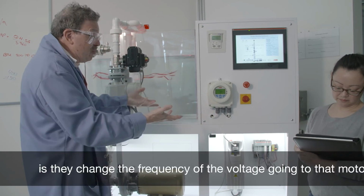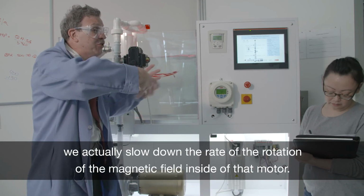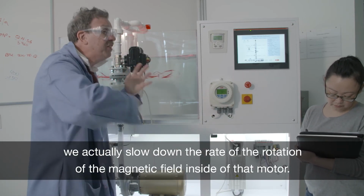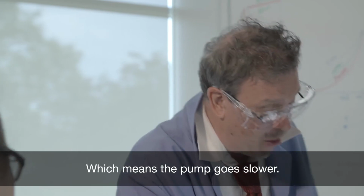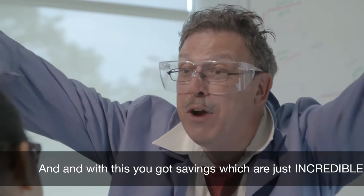But what they do is they change the frequency of the voltage going to that motor. And by slowing down that frequency, we actually slow down the rate of the rotation of the magnetic field inside of that motor, which means the motor slows down, which means the pump goes slower, and with that you get less wear and tear on the pump, and with this you got savings which are just incredible.